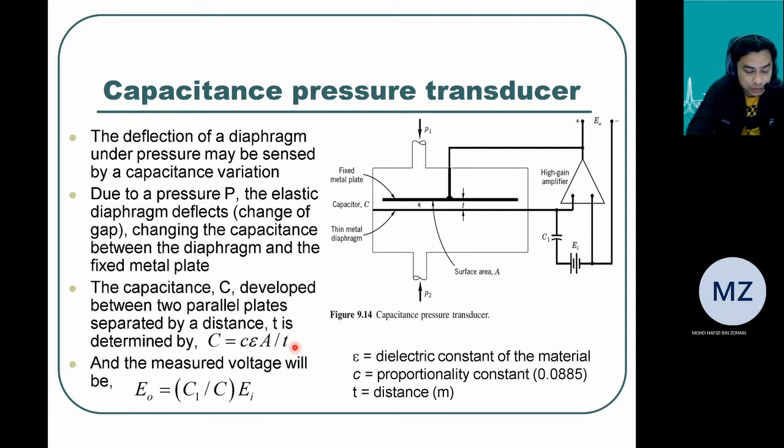Okay, so from this equation, just plug in all the values and then we can find the C. That C here is linearly related with the strain. So the more strain, the more you can increase the value of C, the capacitance. Okay.